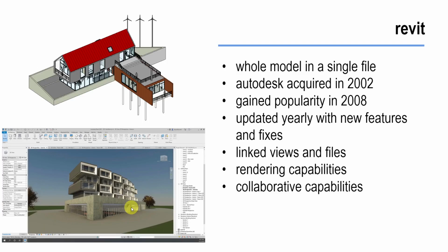And finally, another great thing within Revit that unfortunately we're not going to have time to explore is some of its collaboration capabilities. So within Revit are features called work sets, and essentially within those work sets, you can have several users in a file simultaneously working on it, and that can really help expedite a process, especially for very large firms working on very large buildings. They can have someone working on all of the electrical and lighting plans while someone else also finishes out the foundation, and maybe someone else is working on the facade of one particular side.